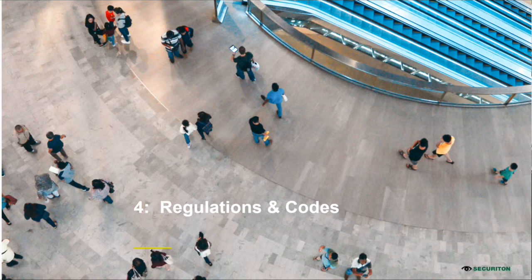Okay, the next question is, is there any length restriction of the pipes laid in the data center? No, there is no restriction on the pipe length, but you have to check the relevant codes applicable in the country where the system is going to be installed, because if you talk about NFPA or VDS or EN, they have certain guidelines. Like NFPA says a single detector can cover only 2000 square meter of area. And if you want to cover more area, then you have to have another detector. So that is one limitation.